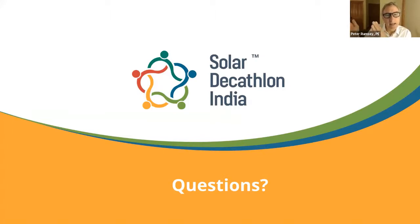When it's humid, we not only have to cool the air down, we also need to dehumidify the air, and it takes cooling energy to dehumidify air. The way we normally dehumidify air is by cooling it down, usually to somewhere in the neighborhood of 13 degrees Celsius, so that the water condenses out, and then we bring it into the space. Typically, if we have a space temperature of 23 or 24 degrees C, that results in about 50% relative humidity. So that's how we dehumidify.